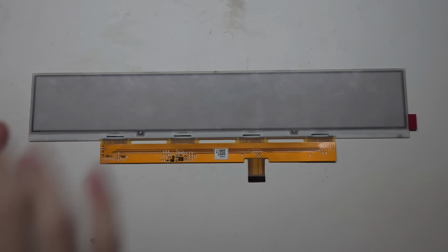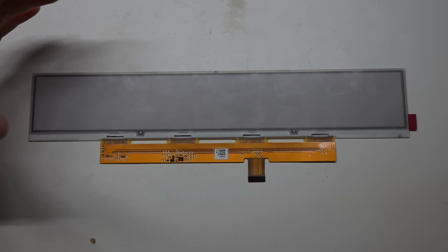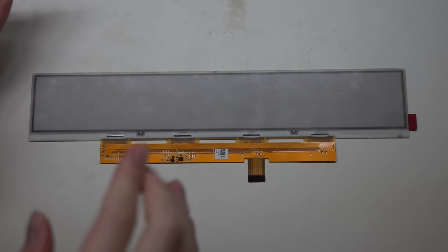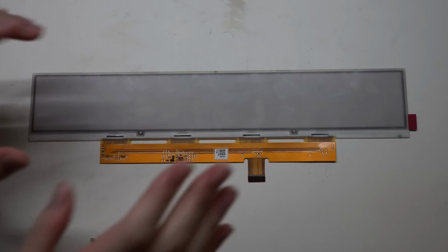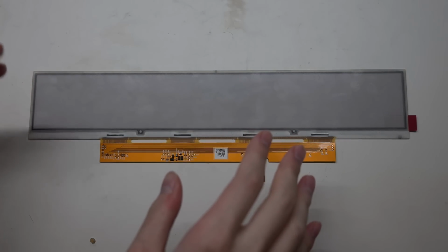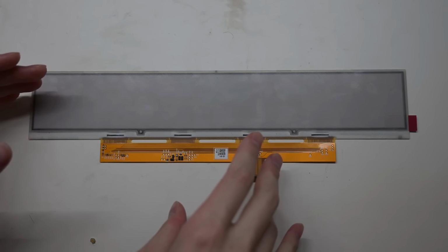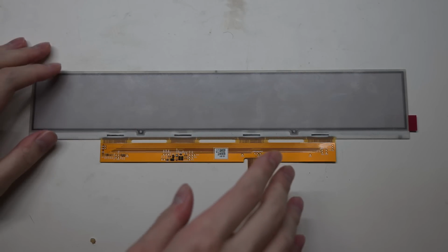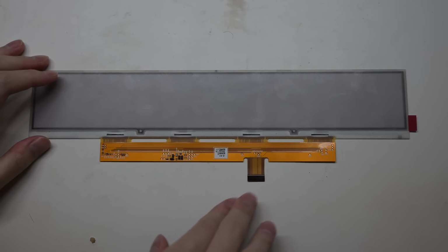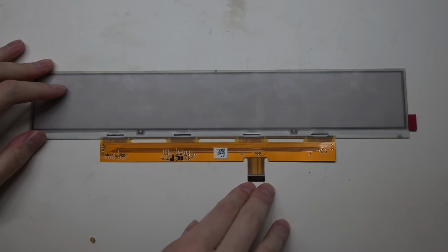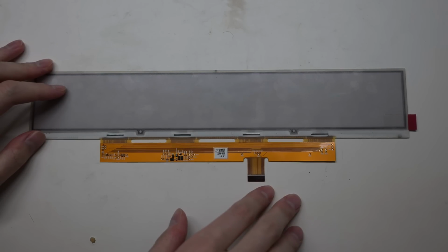Similar things are happening with larger screens like 7.8 inch, 10.3 inch, some of the 8-inch screens, they all share the same pinout. This also applies in the LCD world as well, even though LCDs might be made by different manufacturers, they kind of just copy the pinout of each other to be compatible, for good reasons. But unfortunately, that doesn't apply here. I don't find any other similar screens with the same 25-pin connector, so that's not an option for me.